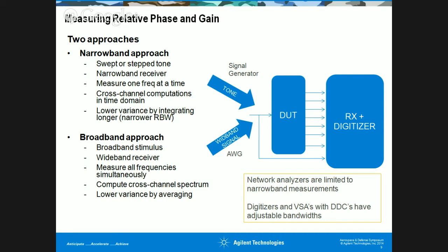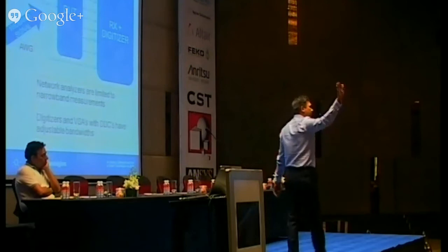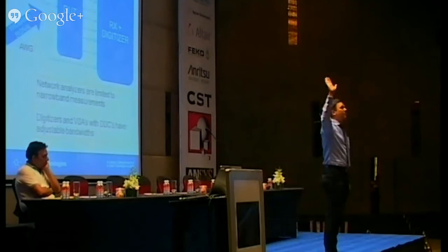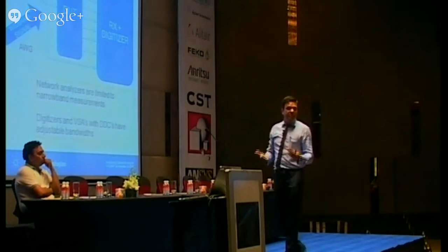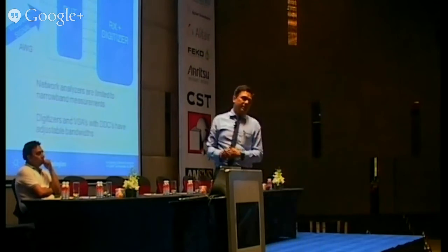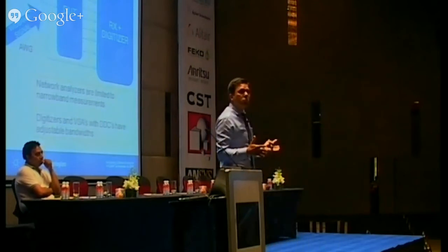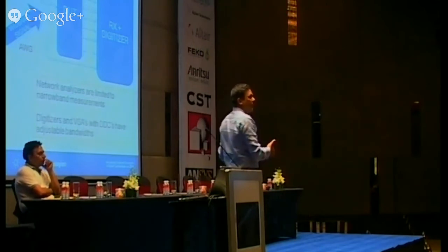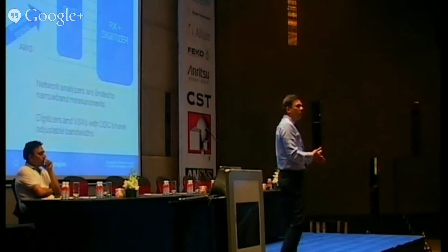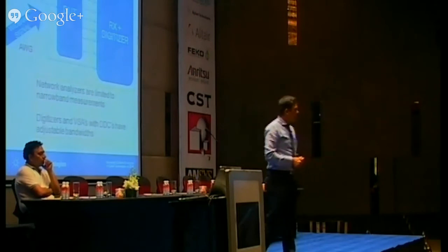A narrowband approach, a question for the audience here. How many of you use a network analyzer for antenna measurement? Network analyzer for antenna measurements. That's the oldest technique. That's the most prevalent technique for doing antenna testing. A network analyzer is used for antenna testing, for its radiation pattern testing, for its gain or directivity testing, in an anechoic chamber or maybe in a far field.